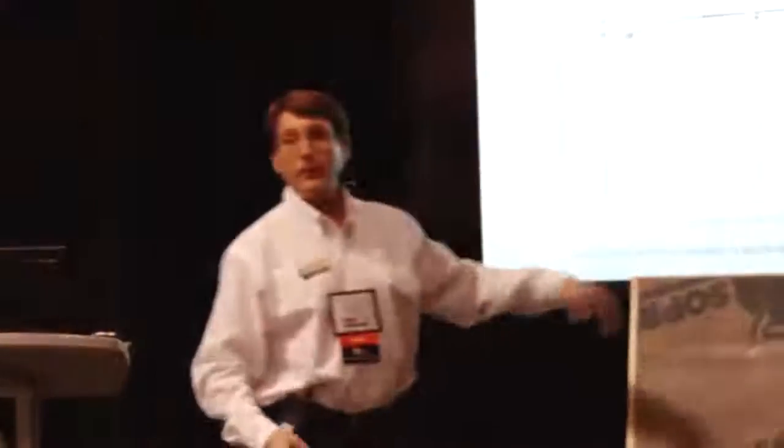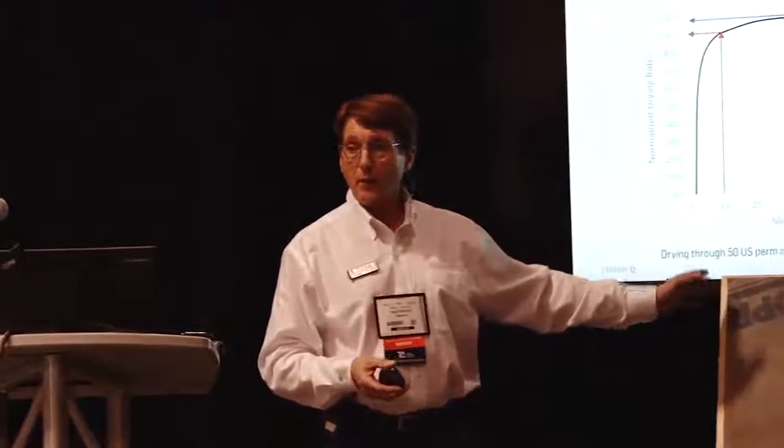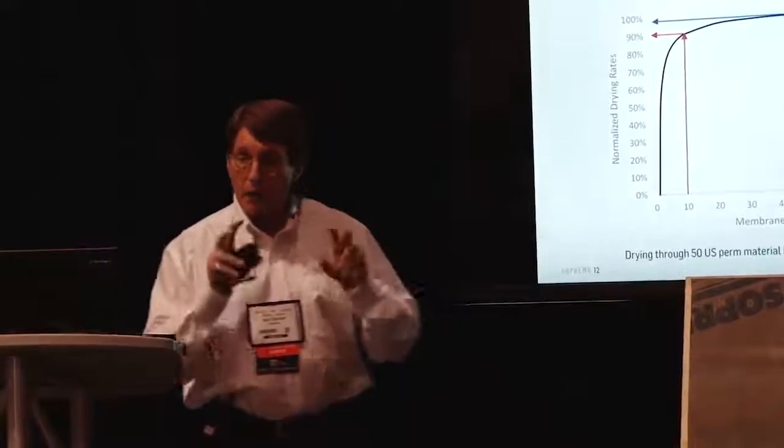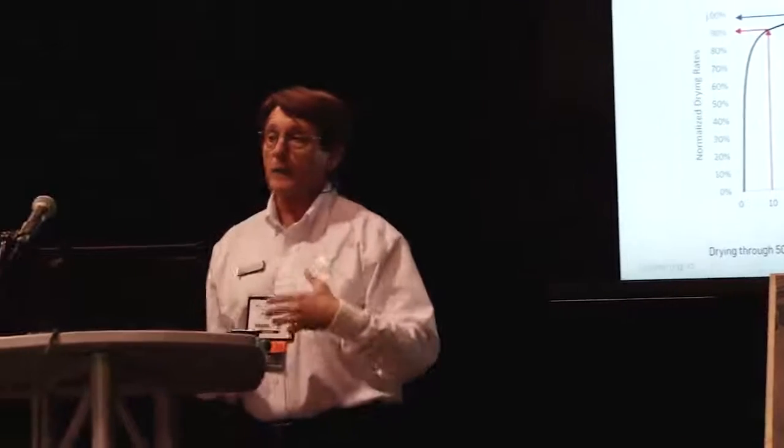So there's not a lot of value in saying I have to go with something extremely high in terms of permeance from the ASTM E96 standard, which tests the permeance of materials. There are 3 classifications, and the third one is 10 perms. So 10 perms is a realistic value for a membrane to have to get an appropriate drying time or drying rate.